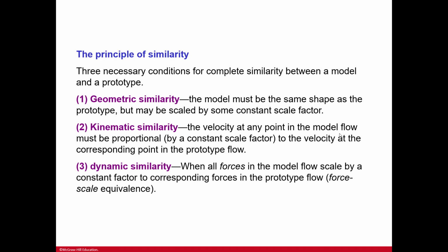And then dynamic similarity, when all forces in the model flow scale by a constant factor to the corresponding forces in a prototype. Force scale equivalency. So you just want the same environment, the same forces, the same geometric similarity, the same dimensions, all of these things, you want it to be the same, just on a scaled number, right? That's what you want. This is incredibly important and incredibly easy to make a mistake.